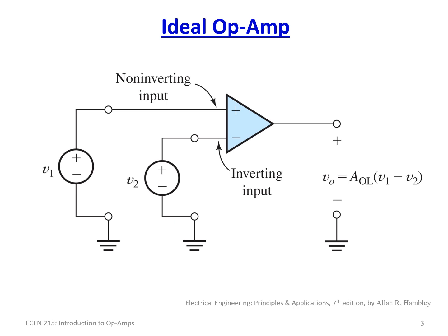We have this triangle that represents the amplification part, where we take some sort of an input, and we have a non-inverting input and an inverting input. We take the net difference between the two and amplify it by some value, known as the open loop amplification, AOL.